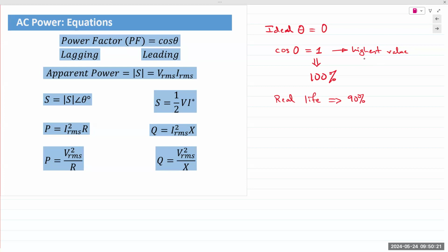Circuit breakers essentially trip if the current being pulled by the load goes too high. We used to have fuses, but every time a fuse blows, you have to go and insert a new one. Circuit breakers, relays, just trip. Then all you have to do is rectify your issue and turn it back on. So yes, absolutely, current requirements.